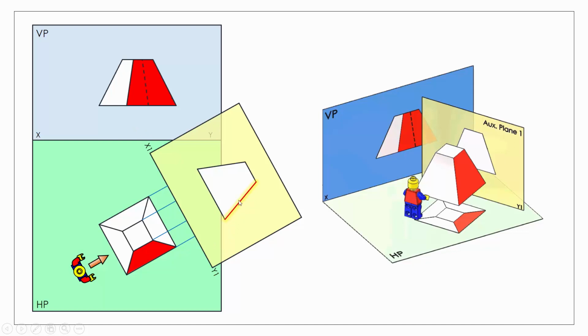Now you only need to draw in this particular surface here. You don't necessarily need to draw in the entire object. I'm going to do it in this example here just to make it a little bit clearer, but usually if you're projecting an auxiliary like that, just project the surface that you're looking for. But so on your sheet we're going to continue our lines like so, and we're going to take our heights from our elevation and project them onto, or transfer them to, our auxiliary.